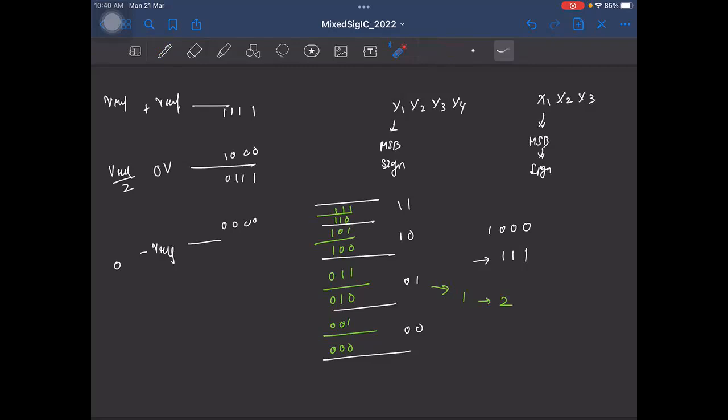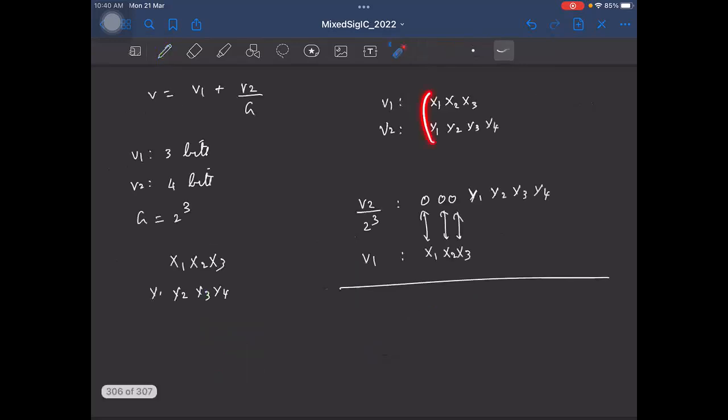The simplest way to think of it is like this: let's say you have plus 0.5 and plus 0.025. You will add them aligned by the decimal point. You will not add them like plus 0.5 and 0.025 lined up at the end, isn't it? So the MSB is essentially giving you the decimal representation. That's the point you can think of. So that's why we need to align these two MSBs and not the LSBs.